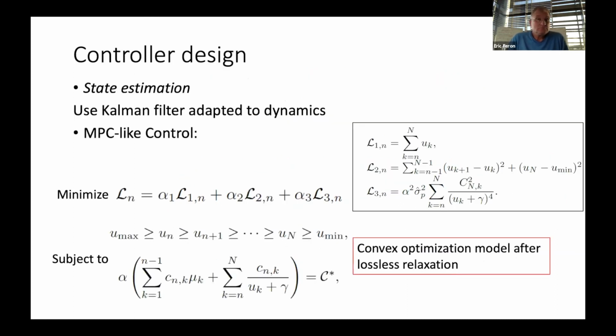Now, when we have a model of the beam building process as a noisy process, which is read by noisy measurements, we have the ingredients for making a state estimator, which is not much different from a traditional Kalman filter adapted to the time-varying dynamics of the beam, since the state changes at every time step.